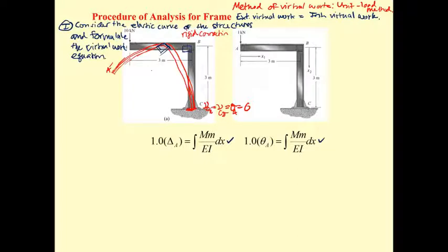What we have is the vertical displacement, which we call V sub A, V at point A. This one is the horizontal displacement at A, H. And the last one is the slope, zeta sub A. Each point of the frame is going to have three of these; it's called degrees of freedom.